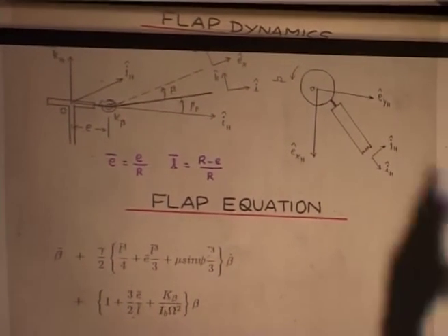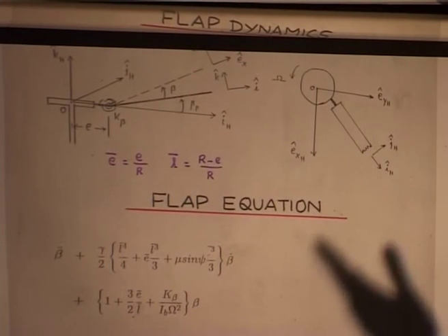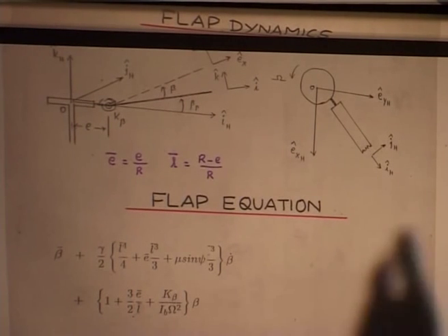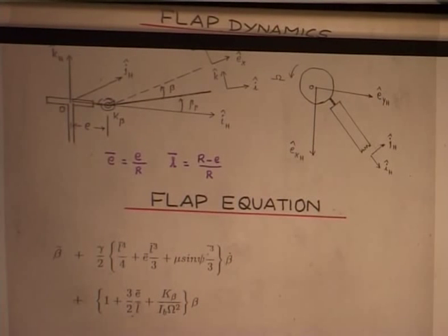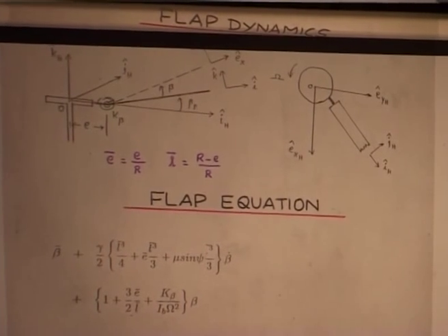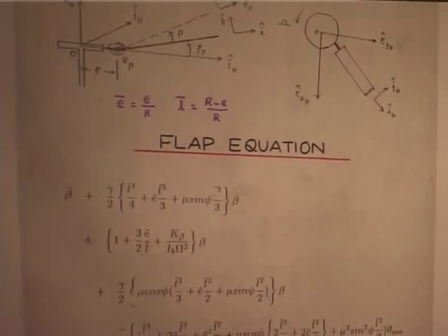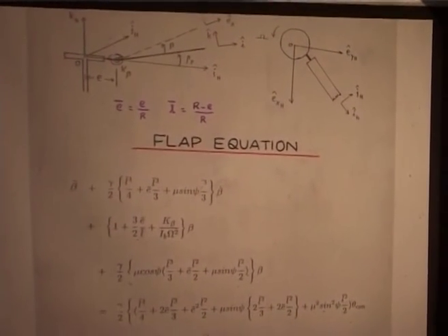When the rotating flap frequency goes up, the hub moments go up and you get more control moment at the fuselage. So, that is how the flap frequency dominates your design really. Flap frequency is very, very important, and you can have different types of rotor heads like articulated or hingeless, etc.